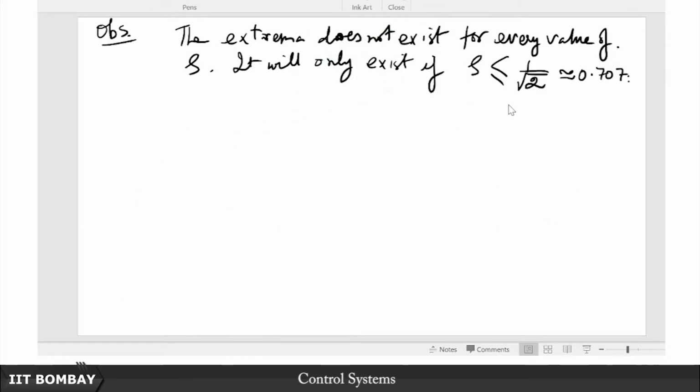So in other words, in the time domain, a way of specifying zeta indirectly by visible parameters is percentage overshoot, something that even a lay person can see by looking at a step response. A lay person can just tell you, okay, this is the percentage overshoot that is acceptable. Immediately a control engineer will translate it to some constraints on zeta.